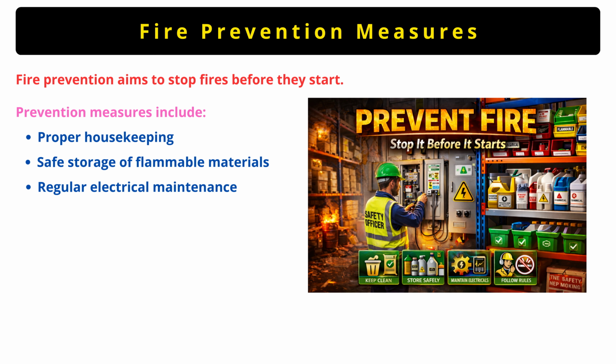Third is regular electrical maintenance. Electrical faults are a major cause of fire. Loose wiring, overloaded circuits and damaged cables can act as ignition sources.